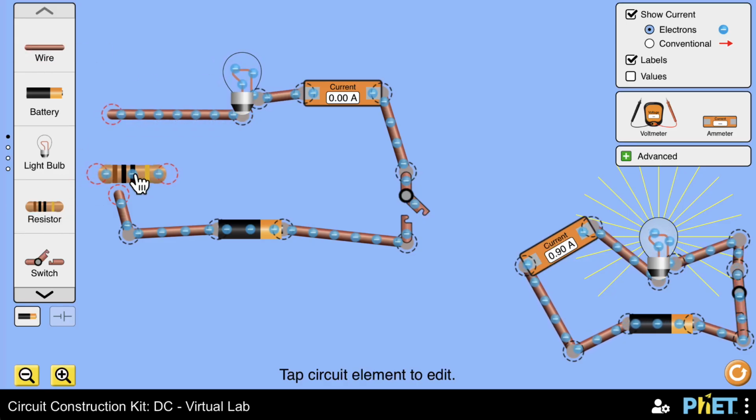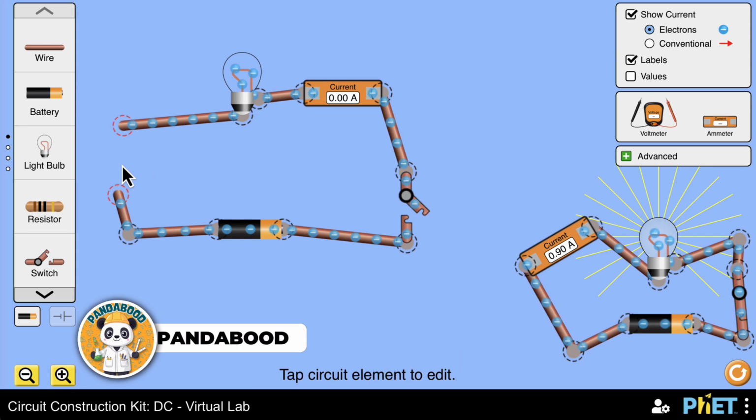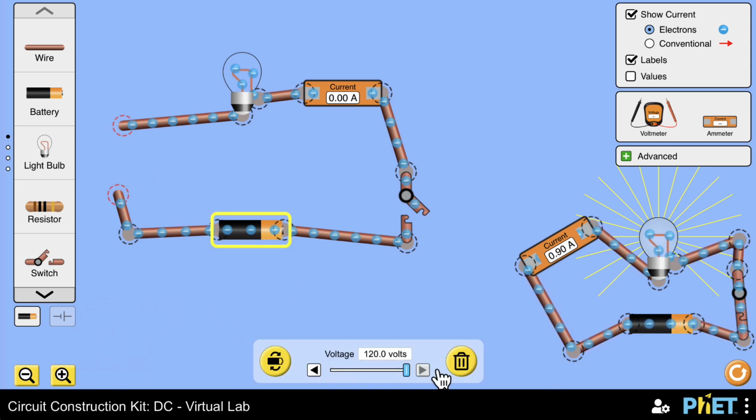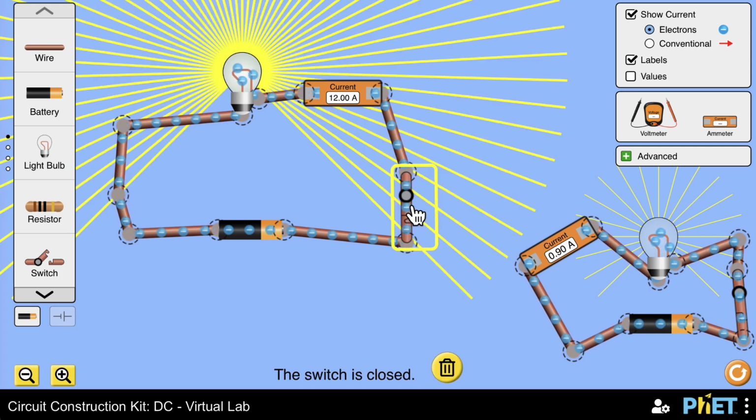Let's bring in this device, the resistor. Now from the name, some of you might guess, this resistor adds some resistance to the circuit. So let's say you cannot actually change the resistance of this light bulb. And let's say you have a very big battery, like 120 volts. If you don't have a fuse and you turn the circuit on, luckily it's not burned, but this is so much brightness. You don't want this brightness. You have 12 amps here and this is more than what you want.